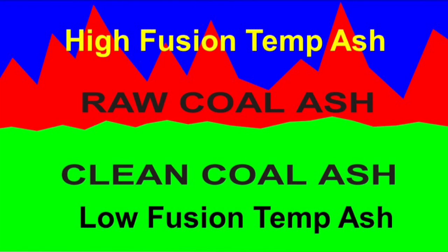Another phenomena that has occurred is that the material or the ashes that are associated with the coal tend to be low fusion or things that lower fusions. Calcium, sodium, iron come to mind. And then the out of seam dilution or the rock material that might get mixed in with the coal tends to be higher fusion material. And so again, you see a fluctuation of the fusions. But I'm just going to suggest that when you put more ash into a coal, you didn't take any of the low fusion material away. You diluted it with some other material that could indeed melt or incorporate into a slag deposit.